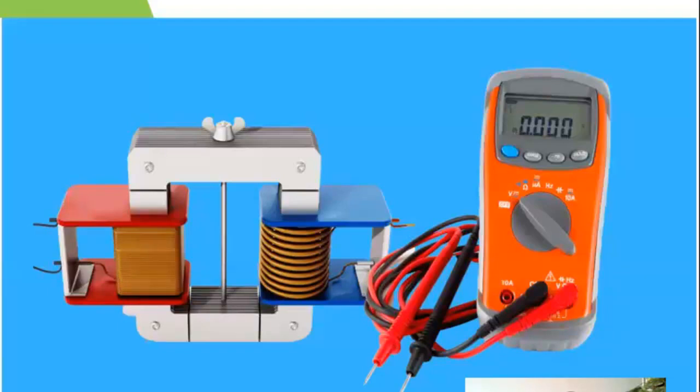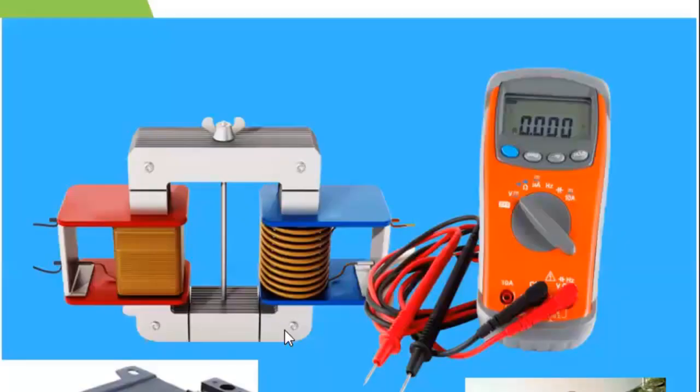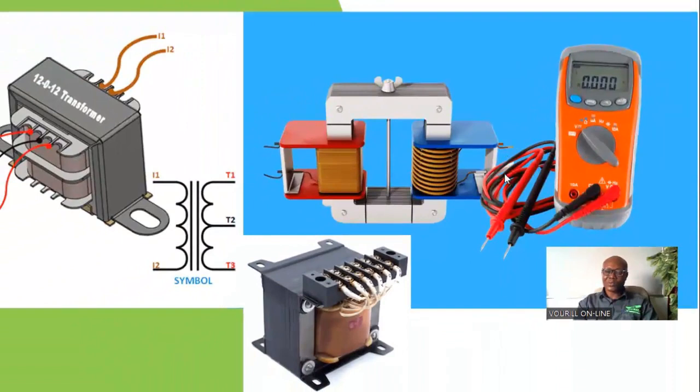Okay, so on the secondary part too, you can test winding to ground. Okay, then like we said earlier, you can do live tests, which means you power the transformer by supplying input to the transformer and then testing the voltage output from the secondary. So you should have the expected output from that particular transformer. If you are not having it, that means there's a problem with the transformer.